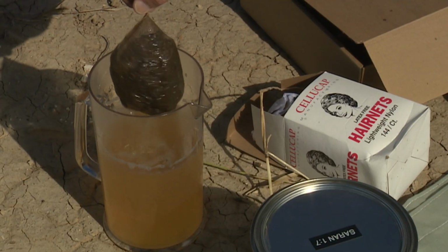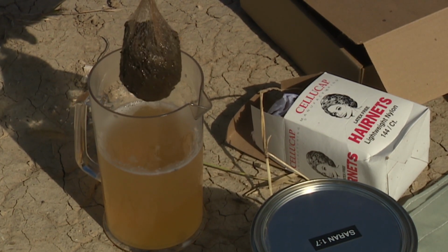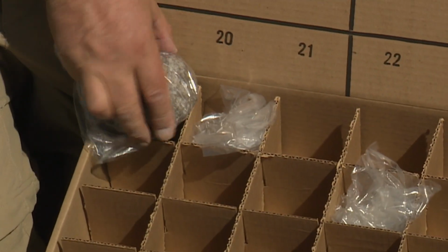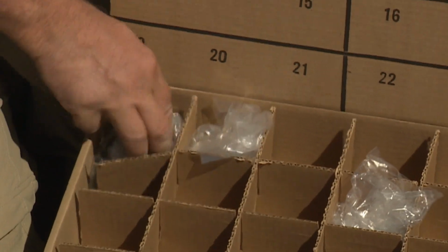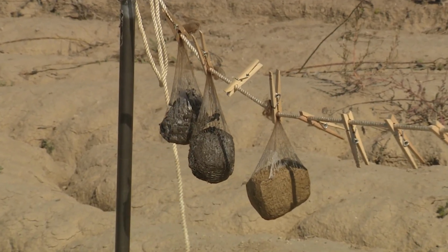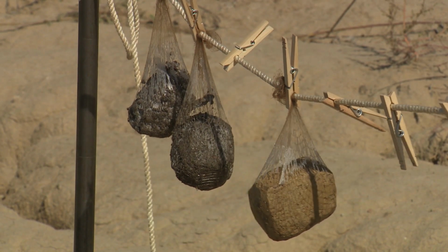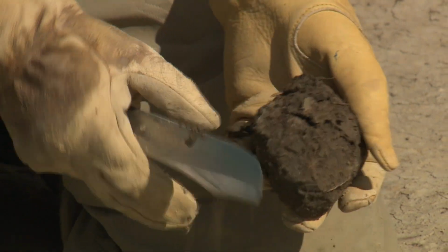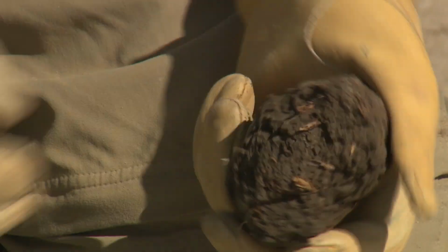An experienced soil scientist can help you select the proper method and technique for collecting bulk density sampling. This job aid is designed to help you match the appropriate bulk density sampling method to various site and soil conditions. The clod bulk density method is the most widely applicable method and is the preferred method because clods have the advantage of being used to produce water retention data and to measure COLE. These items cannot be measured from samples collected by the known volume can or compliant cavity methods.